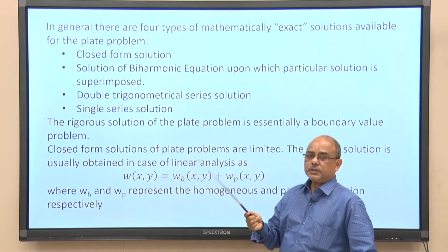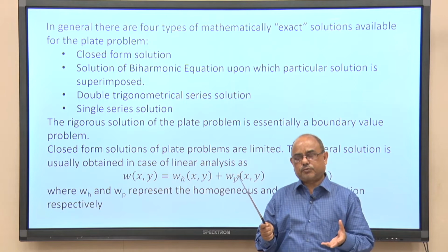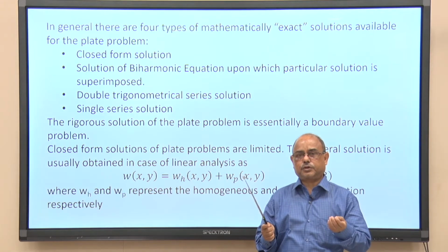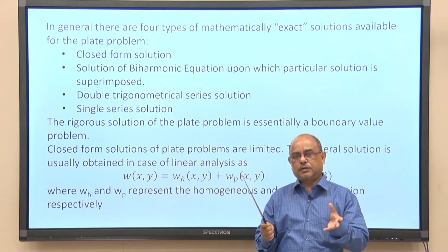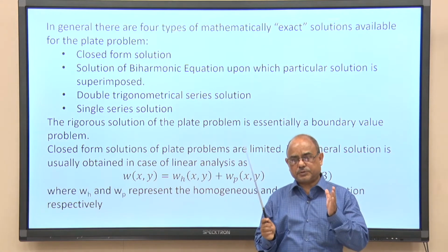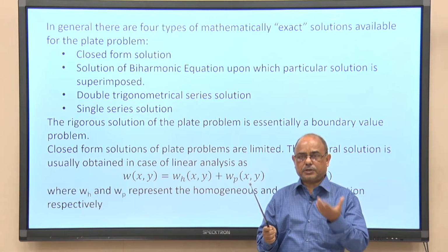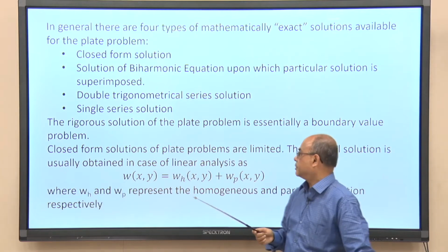Now, in certain cases the trigonometric series provide a very useful way of finding the exact solution of the plate problem for specific boundary conditions or for specific loading. Especially for some specific boundary condition, single trigonometric series or double trigonometric series can be conveniently used to find the closed form solution. Okay.